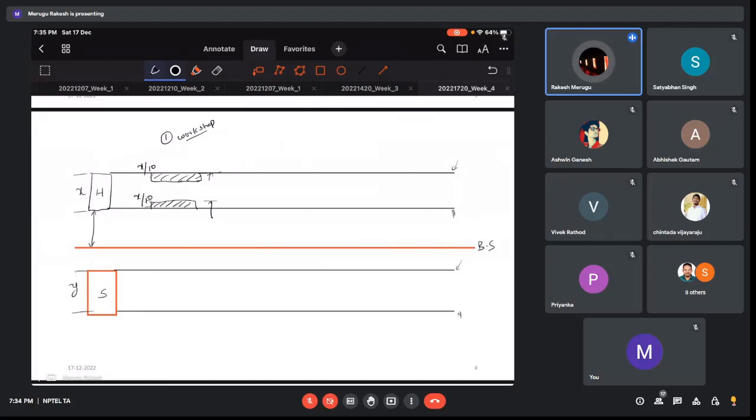So that's why we have to provide the wear on this. This wear is x by 100, the one-tenth of the gauge tolerance. On top I will have the gauge tolerance, and there will be no wear allowance for the no-go gauge. So this is workshop gauges for holes. The same diagram will be there for the shaft, but inverted. I'm not writing it for the sake of time, but it will be the opposite. This will come here, this will be here.